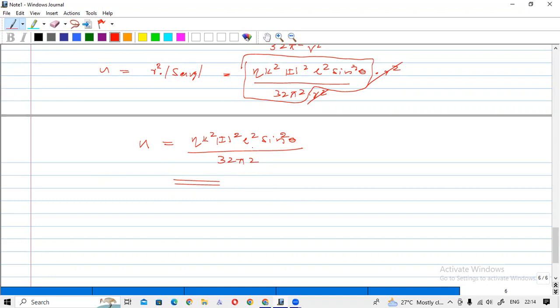So you can see that the radiation intensity is not uniform, because it is changing with theta. If you place this antenna like this, theta is the vertical angle, this angle, and phi is the horizontal angle like this. Phi we normally refer to as azimuth. Theta is the tilt.